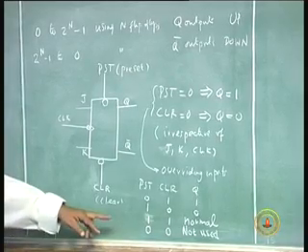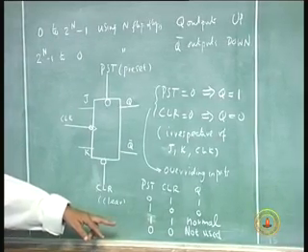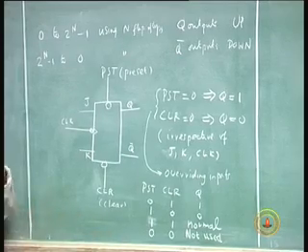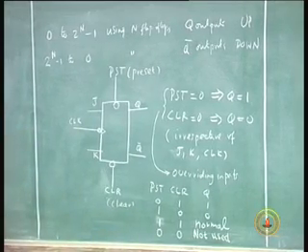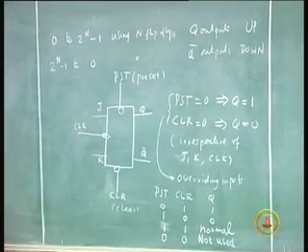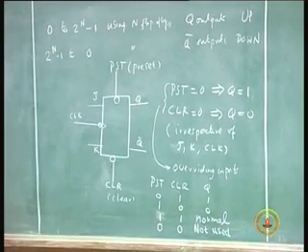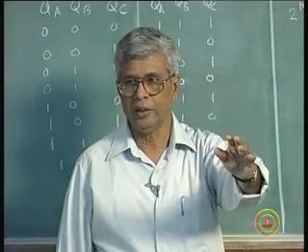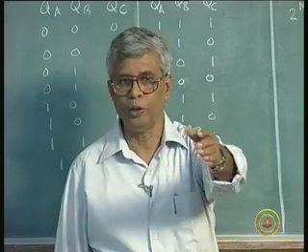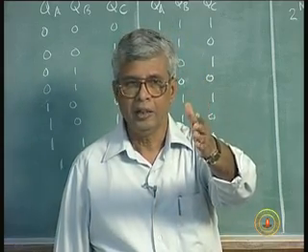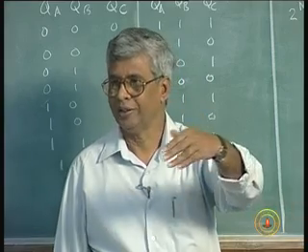Now, this property is going to help me to start or count anywhere I like, and end my count anywhere I like. Suppose I go from 0 to 2 power n minus 1, and at some intermediate point I want to terminate and make it 0 0 0. I can do that by detecting that point and clearing all the flip flops at that point.